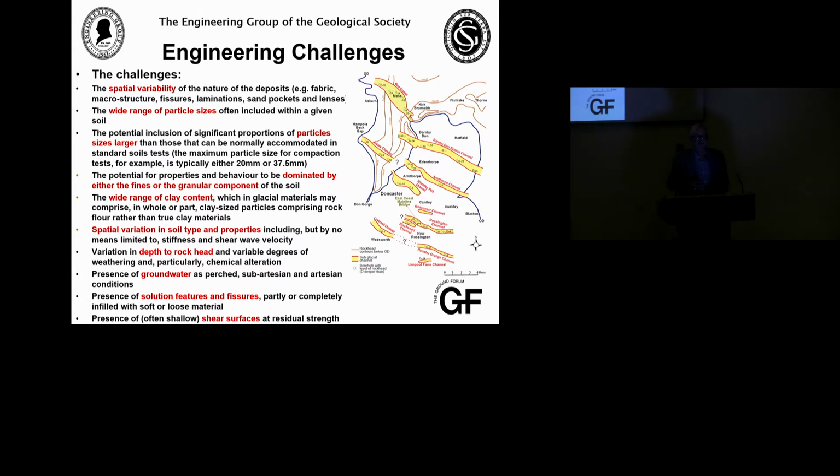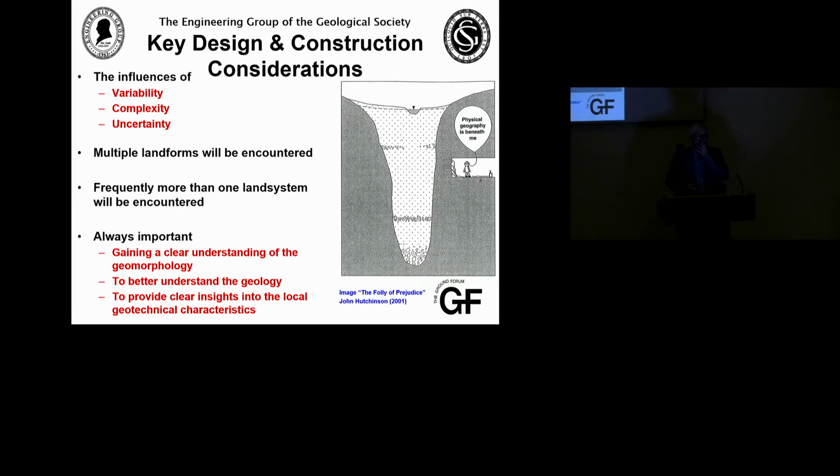Who'd have thought that around Doncaster, the M1 had such a complexity of terrain with this entire paleo valley system that was present? Maybe completely miss it on a borehole investigation. If HS2 does its boreholes at 3 miles apart, you're going to miss these kinds of features. We're now at the 1 metre, the 10 metre, the 25 metre scale. If we don't have our conceptual model, we won't understand the engineering challenges in that particular ground profile.